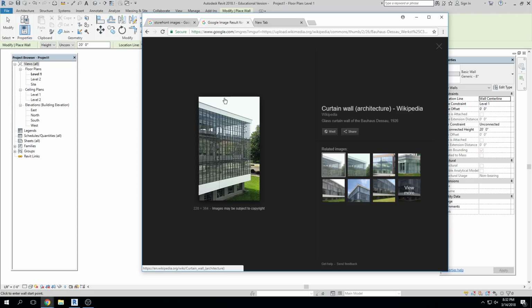Okay, and usually this is meant to span multiple stories of glass, right? So like this image here, you see these really big multiple stories of glass, okay? To hide these areas, you'll have a little piece called a spandrel piece of glass where it's not vision glazing. So you can't see through it, so you hide the connection. And then if you're a little person standing down here, you can look up into the building, okay? So that's the difference between storefront and curtain wall in the real world.